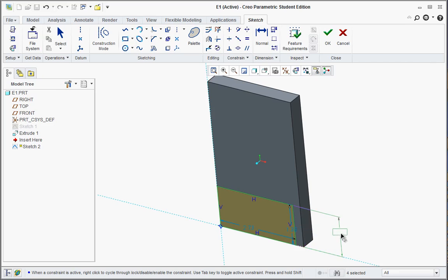Now you get the dimensions, so we get the height and width. You could type in an explicit value for the width, 3 inches, then it would be equal. But that kind of goes against the whole premise of parametric modeling. You want everything to update together, especially if you know the design intent was to actually have both update or be the same width. So we'll leave that width alone for a second, and I'll show you a solution for that. But this needs to be 1.5, so that's for the height.